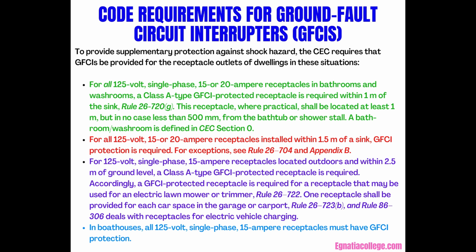One receptacle shall be provided for each car space in the garage or carport, Rule 26-723b. And Rule 86-306 deals with receptacles for electric vehicle charging. In boathouses, all 125 volt, single phase, 15 ampere receptacles must have GFCI protection.